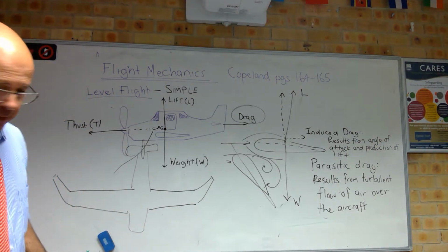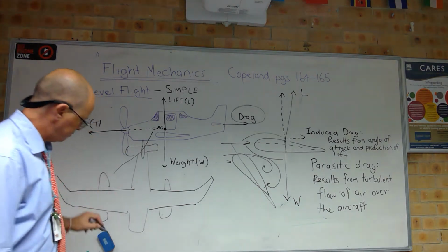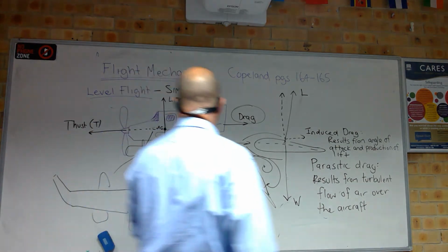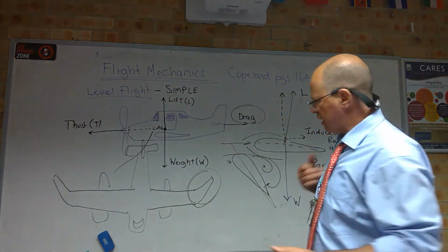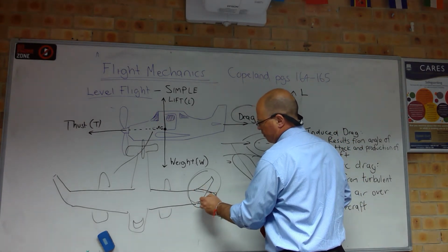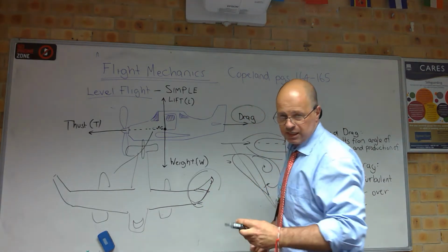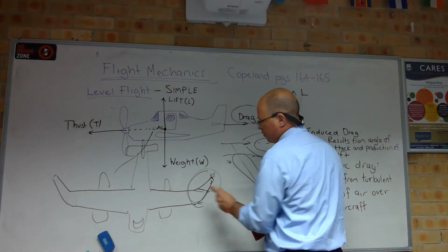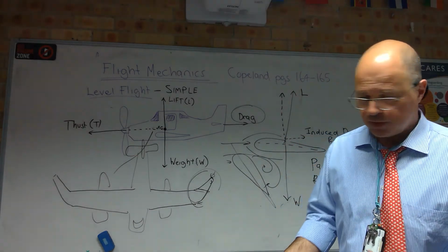So that is a swept back design. This sweep back at the end of the wing does exactly the same thing. It takes that wingtip vortex, which would be out here, and pushes it back behind the wing, okay? So it doesn't affect the wing as much. The wingtip vortex becomes a lot narrower, and it gets pushed behind the wing where it's not going to create as much drag, okay?